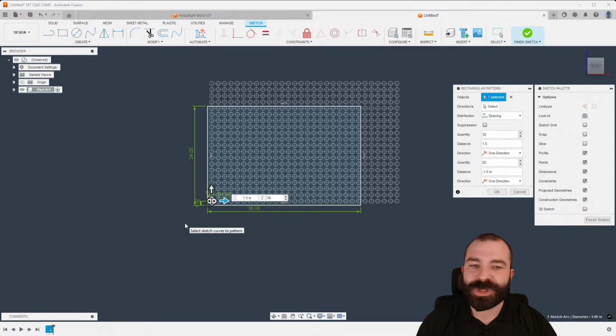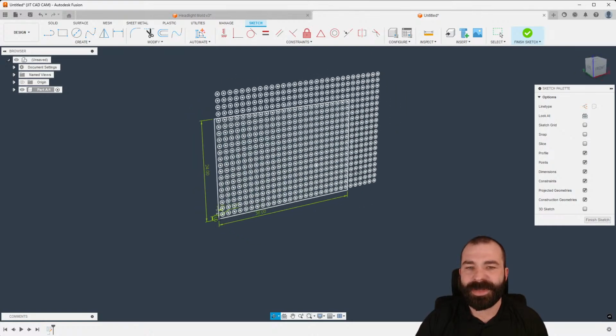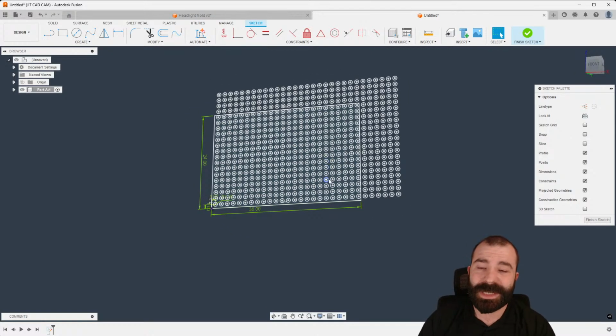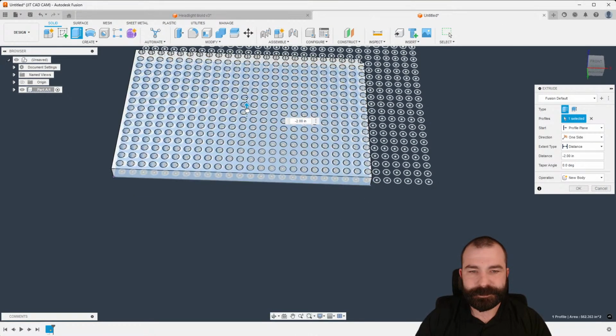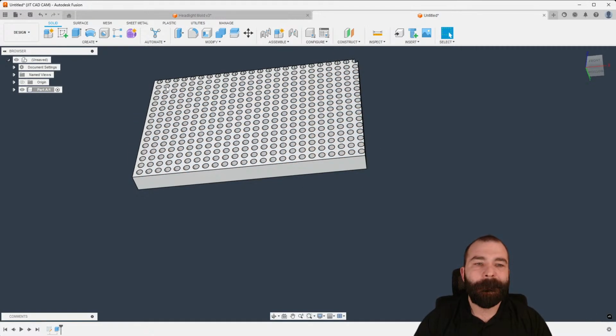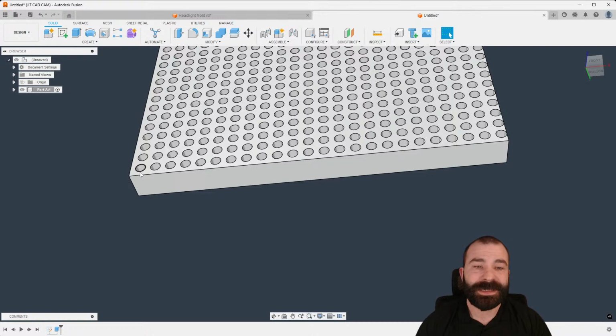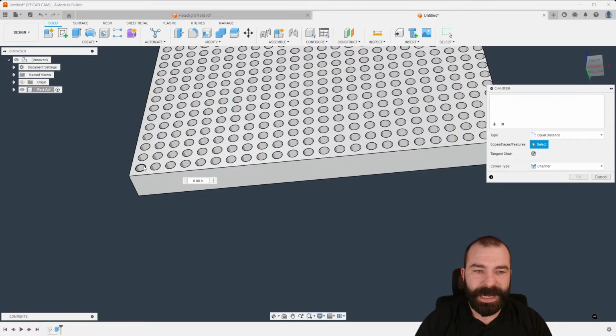But when you're actually going in, in this case, we're building a sketch. We're adding a lot of detail at a sketch level, and your performance will start to get robbed based on the patterning of a sketch. Where this is also a pain, depending on how you're trying to model something, is if you wanted to extrude to create this plate right now, as you can see, I can extrude up to create it, and again, don't judge me on my designs, guys. But if I wanted to now chamfer these, there's a lot of ways to add those chamfers, but it is going to be a total pain because I have to more or less select each and every one.